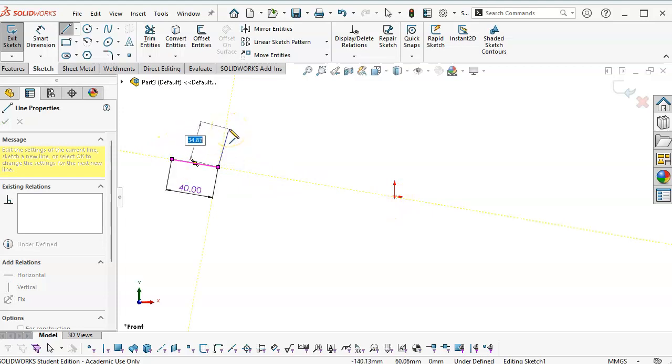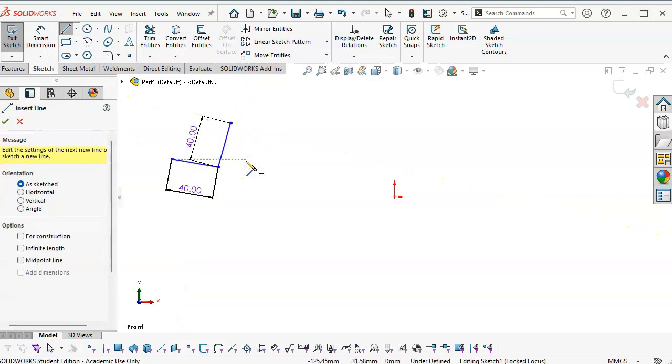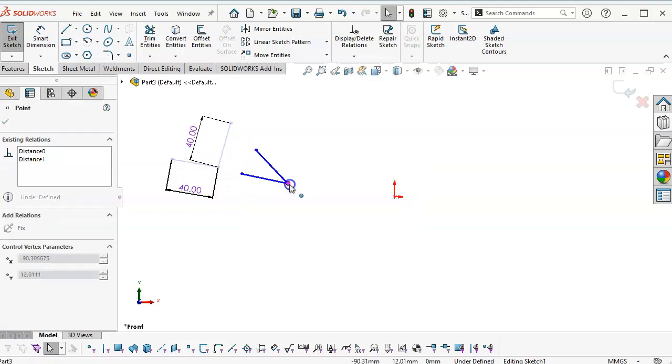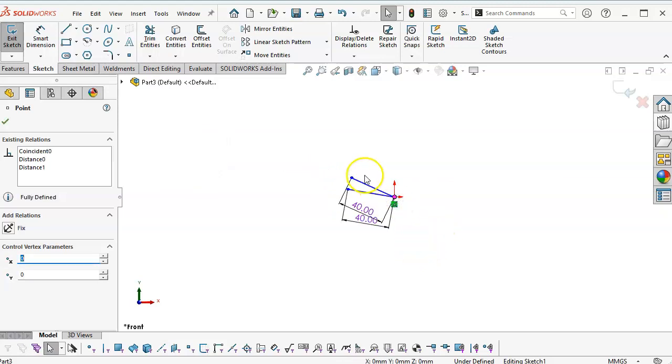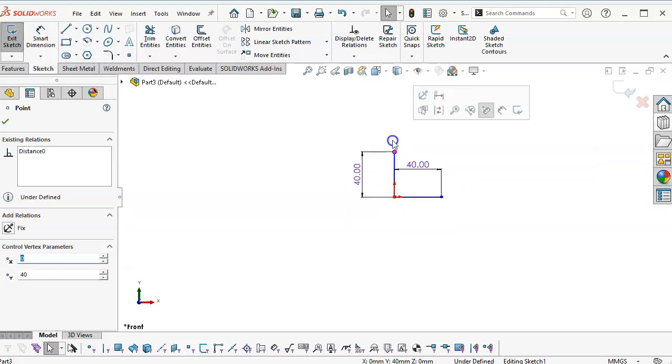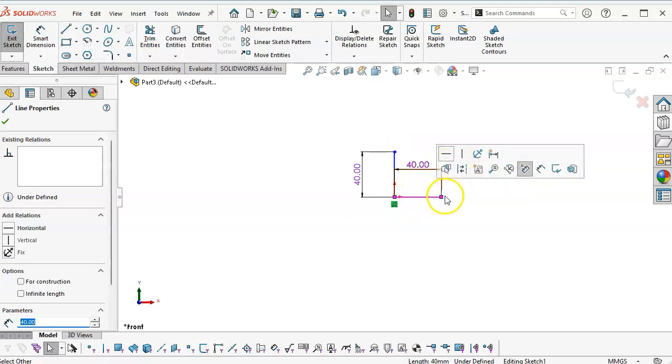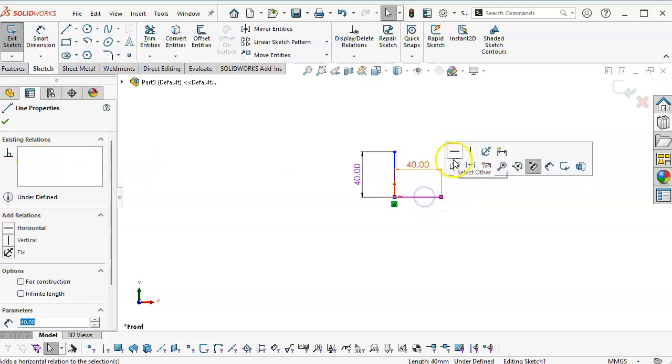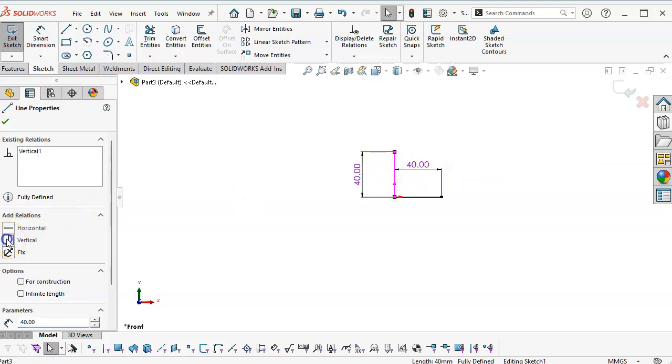So this will be interesting, since I clicked and I'm playing with the sketch numeric input at the same time. With the click, I actually got the double click to terminate it to work. And even though I saw the perpendicular, it didn't stay perpendicular. So worst case, I'm going to bring that one out horizontal, bring that one up vertical. And because I saw the white, but it did not put anything over here in the existing relations, I'm going to apply horizontal, or I'm going to come back over here to the property manager and apply vertical.